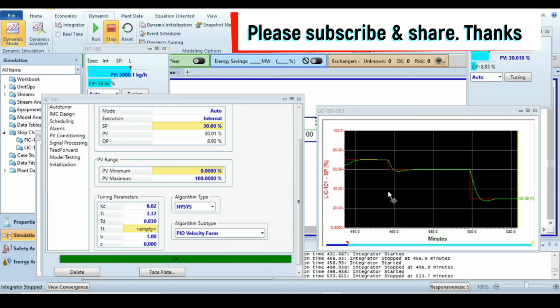The other one is the Ziegler Nichols method, where we calculated the parameters using the empirical relations of the Ziegler Nichols method, introduced those numbers, and got a very nice response of the level indicator controller.